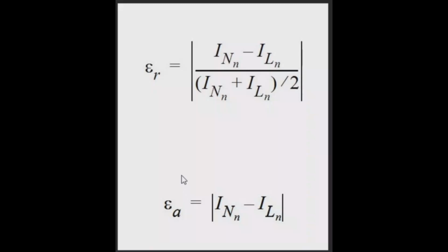You know, we had a guy once who called support, who was very upset because his simulation wouldn't converge. And when the support guy looked at the simulation, he had these errors set to 0. And he called the guy back and said, you can't do that. And the guy said, well, I don't want any error. So that's kind of an extreme example, but that's the kind of thing that happens if you don't understand what the error criteria are.